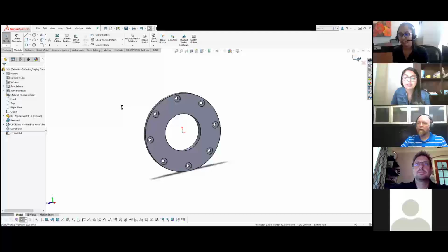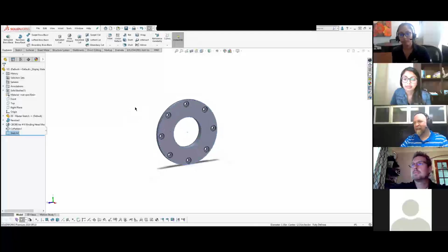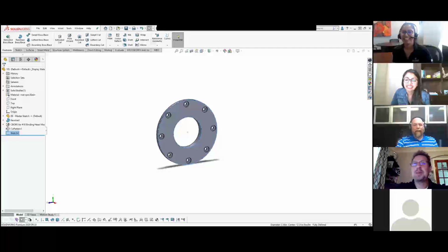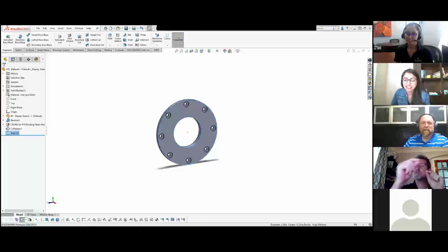What is the best way to define, control, and fix the curvature of a spline? Ray? That's a tricky one. For the most part, whatever the spline looks like, you'll be able to visualize what the curvature combs look like. But we can't actually cause it to twist unless we're in a feature for that. If you're in the sweep command, we do have the option to twist it 180 degrees as we're sweeping around it. But actually controlling the curvature itself, we don't have any real control over that. You just have to find out where it starts and where it ends.